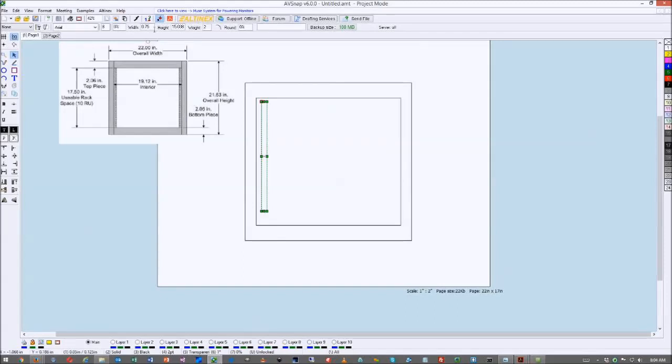So let's go ahead and put 17.5 as a height. So we got our height. We're going to double it because we need one on each side, and I'm going to select the inside rectangle, select the left rectangle, and I'm going to align it to the left, and I'm going to center it. The same thing I'm going to do with the one on the right.